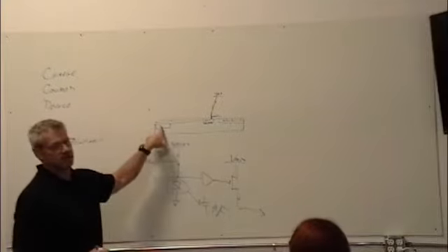So, all right, well, now I've got to put a chunk of gallium arsenide on there. It's like putting down a BGA with the worst pitch you can imagine. Usually what you do on these, they're not balls, they're actually lands, and they'll be aligned like this, so they can be off a certain amount and still get where you want to go. But it's real expensive, because you can't put this on and then dice it. You have to dice all these pieces up. So now you're talking little pieces of silicon this big, but now you've got to come in with a piece of whatever the material is and bump bond it on. And why would it stay? Sometimes it didn't.